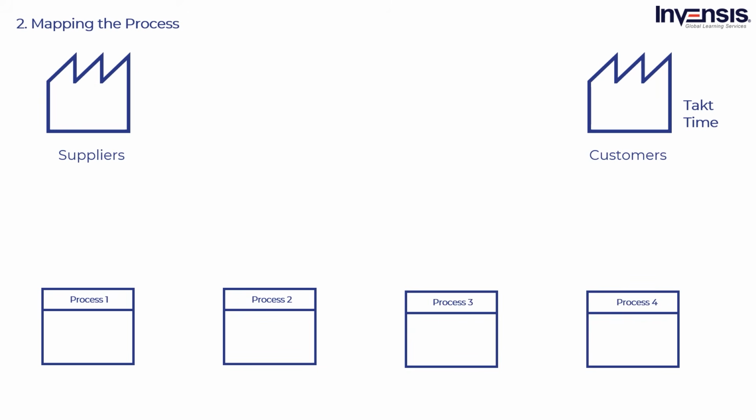It may include information like cycle time, which is the time required to complete that one process. Changeover time is the time required to switch a process to another. Uptime. This is the percentage of time that the machine is running. Next, yield is the percentage of parts that pass inspection. In simple words, it's called efficiency. Along with this, it also includes manual cycle time, queue time, lead time, available time, etc.